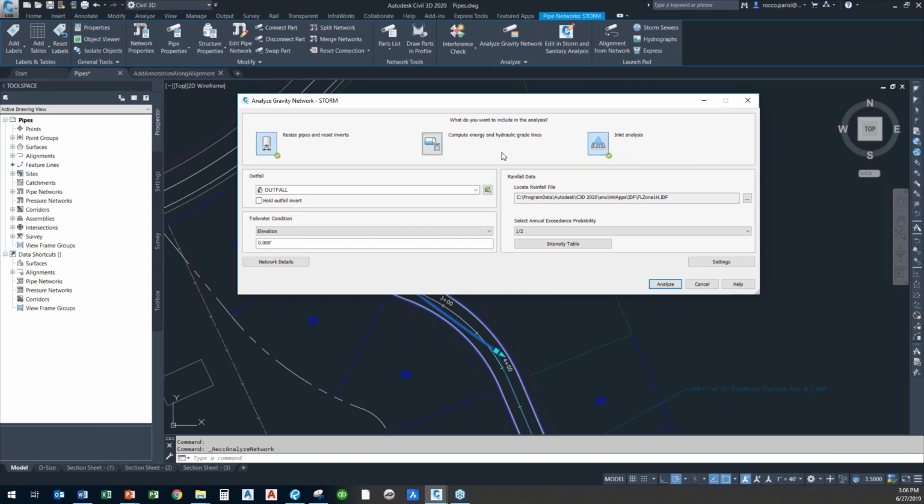If you try to run multiple, you see I can turn these on and off in combination, okay? I can run this and this, I can run all 3, I can run that one and that one. I have found that when you run more than one of these at a time, Civil 3D, not every time, but it has a very high incidence of lockup and crash, okay? So it's not perfect yet. If you need to run pipe sizing and analysis, and you want to do your hydraulic grade lines, they all work nicely, but only run them one at a time.